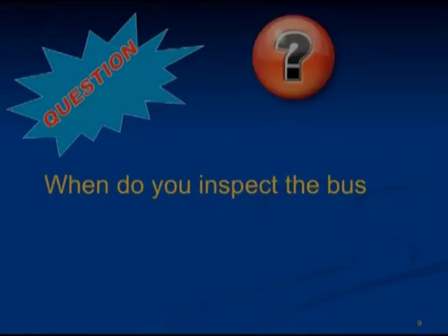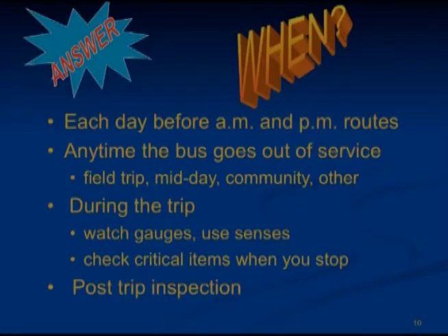When do you inspect the bus? You need to check the bus every morning and every afternoon before each route, including any time the bus goes out of service, i.e., while at a football game, pre-trip before the return trip. If you drive a midday or community trip, pre-trip the bus before putting the bus back in service. You would also check the bus during the trip, watch for gauges for signs of trouble, check the transmission operation, the engine, steering, and suspension and brakes. Remember, use your senses. Look, listen, smell, touch.